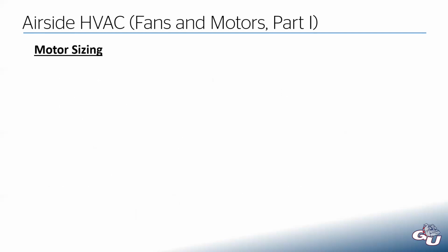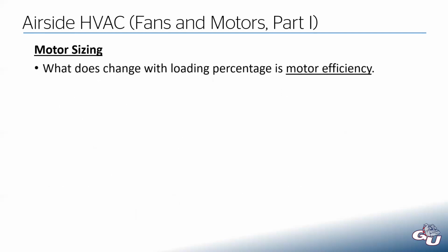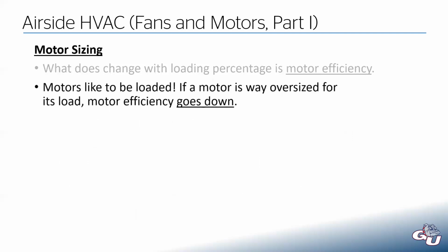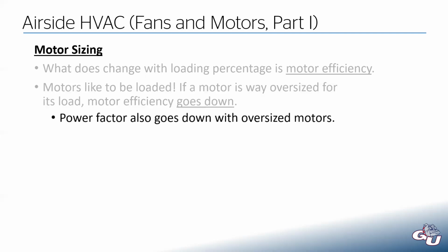What does change though, with how motors are overloaded or underloaded, what does change with that is the motor efficiency. And motors, they like to be loaded. If you have a motor that's way oversized, then the motor efficiency is going to go way down. And as a side note, if you think back to when we were talking about utilities, the power factor also goes down.